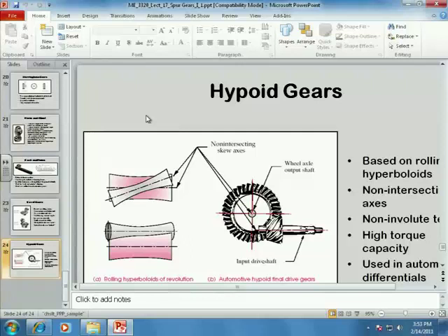So to get the packaging better, you compound it. So you take 2 trains and multiply them together just to get the package smaller. So it's not a hard and fast rule, but rule of thumb, roughly 10 to 1 is a good limit for upper ratio. Your 6 to 1, piece of cake, 1 stage will do it. Don't need to compound it. So all you need is 2 gears. Your choice as to what flavor.